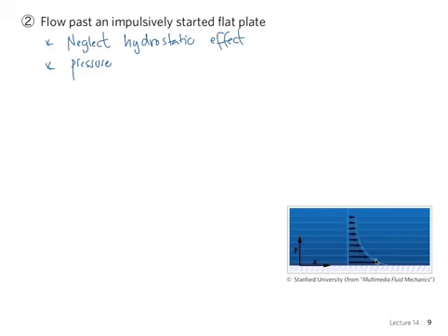Well, it would either be the plate moving or the velocity moving on top of the plate. Either way you want to see it, there is an effect of the viscosity, and there's a no-slip boundary condition right at the surface of that plate. So if the plate is moving with velocity v, that first layer of fluid is moving with velocity v.